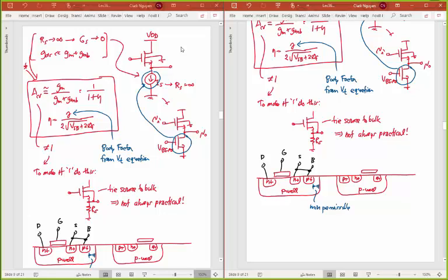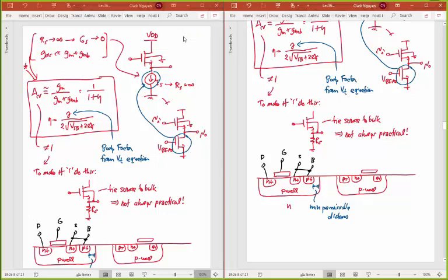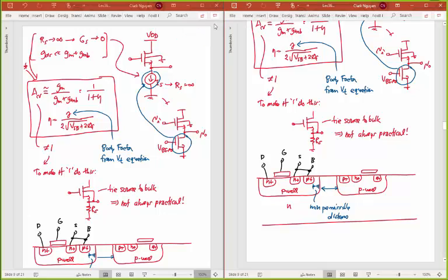Permissible distance between your P plus junction and the edge of this P well that then, of course, goes into this N-type material here. So everything out here is N-type. Okay, and you also need to have a minimum distance then between these two P wells. Okay, they have to be minimum because I'm assuming that you have two different voltages on there. You can't get these any closer.